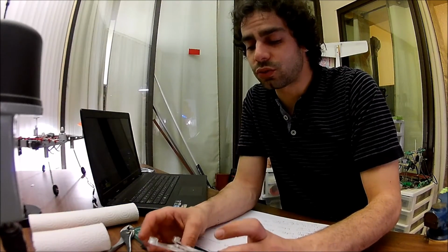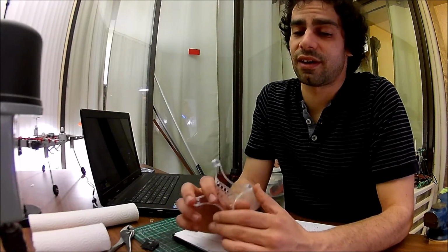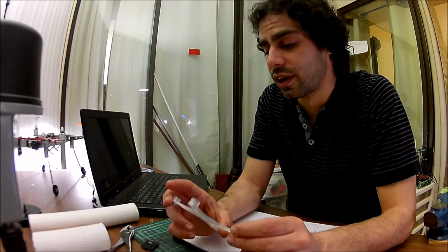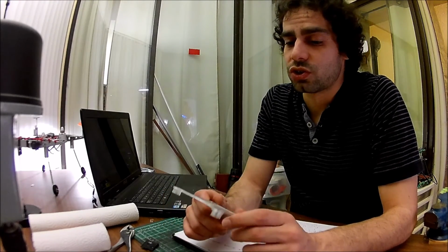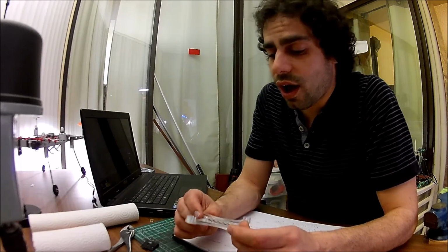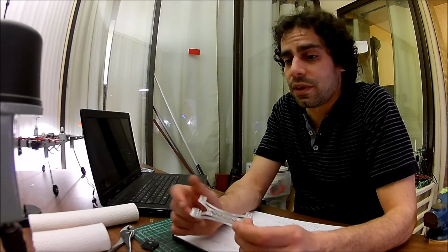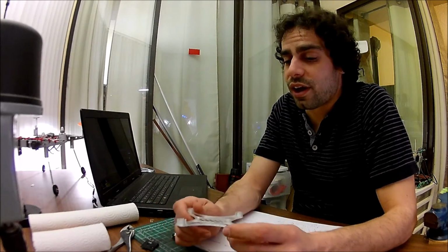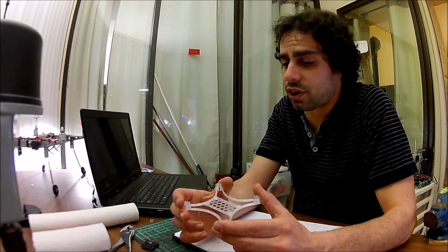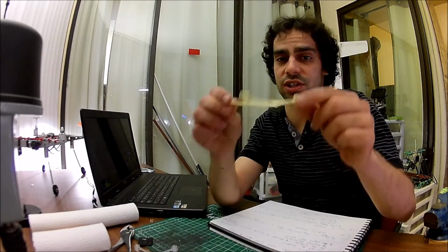When selecting 3D printable materials, the main issue you'll run across in the additive manufacturing process of FDM 3D printing is shrinkage. So what is shrinkage? Shrinkage is basically a byproduct of the cooling process. So as the filament is being laid, it is cooled, and as it's cooled, it shrinks. Some plastics shrink more than others. If they shrink a lot, you wind up getting very warped components such as this.